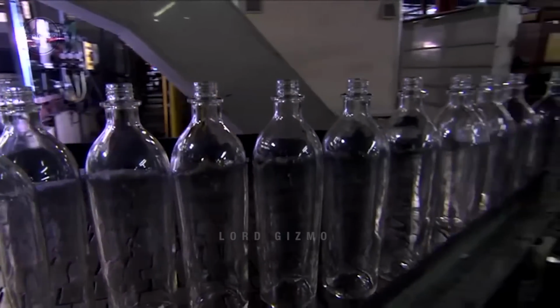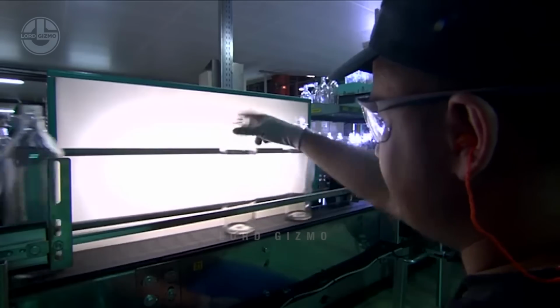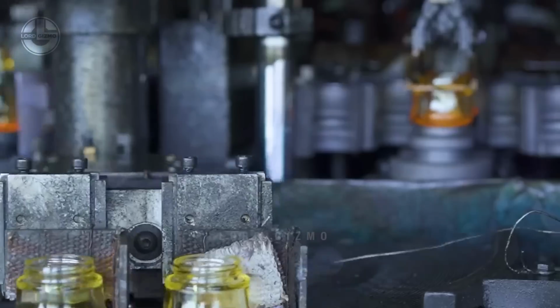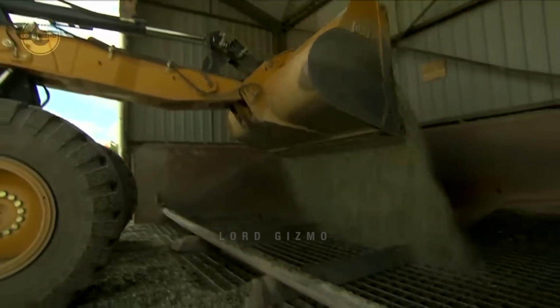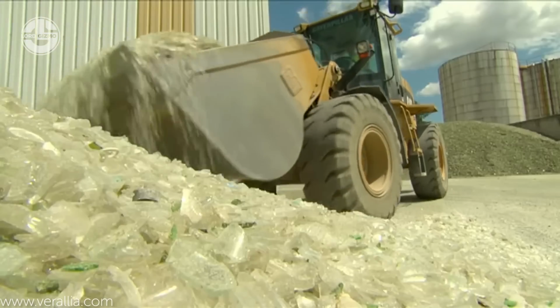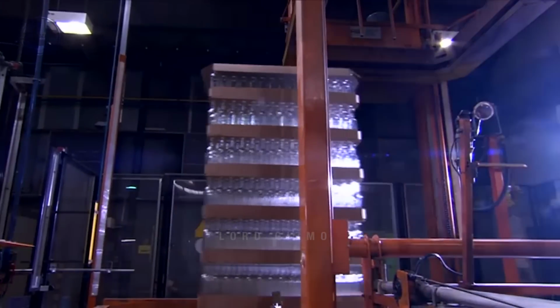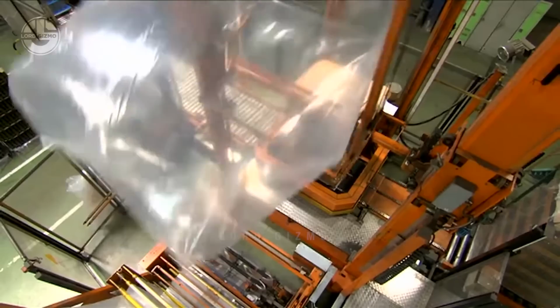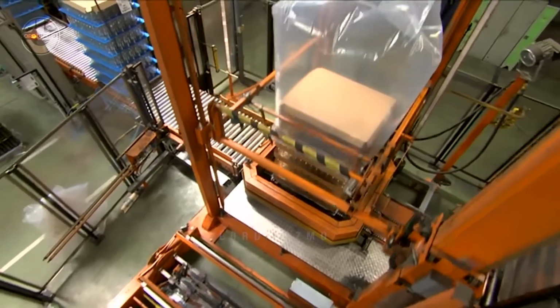One by one, everything is checked, whether it is the split finish, or wall thickness of the glass bottles. Any rejected containers are immediately removed from the production line, recycled as cullets, and used in the fabrication of new glass. Interestingly, glass is the only packing material that can be totally recycled indefinitely, although the packaging bottles themselves must be carefully wrapped before shipment.